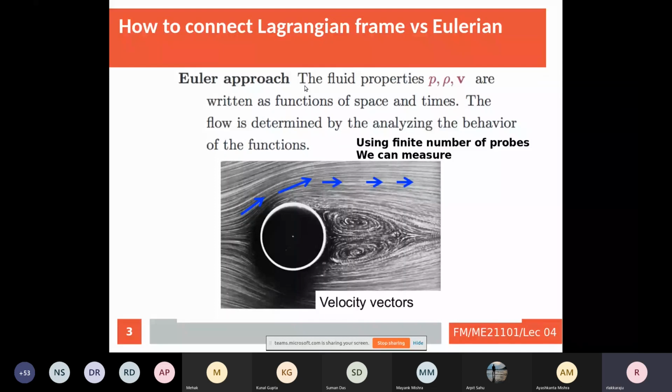So one is the Lagrangian velocity, when you are sitting in the car along with that person trying to monitor the dashboard. You have a radio transmitter, immediately you measure it and transmit that velocity, and the traffic constable gets it. At the same time, the traffic constable shoots this laser to find out the velocity. These two velocities are supposed to match at that given space, at that given instant of time.